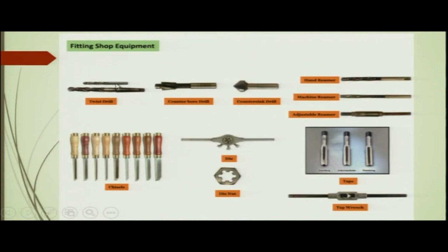In this case you can see that this is the cylindrical shank, and for this drill, where the diameter is more than the previous one, this taper is the Morse taper, all right. The holder for this kind of drill will also have an internal tapered hole, and that internal taper will also be a Morse taper.